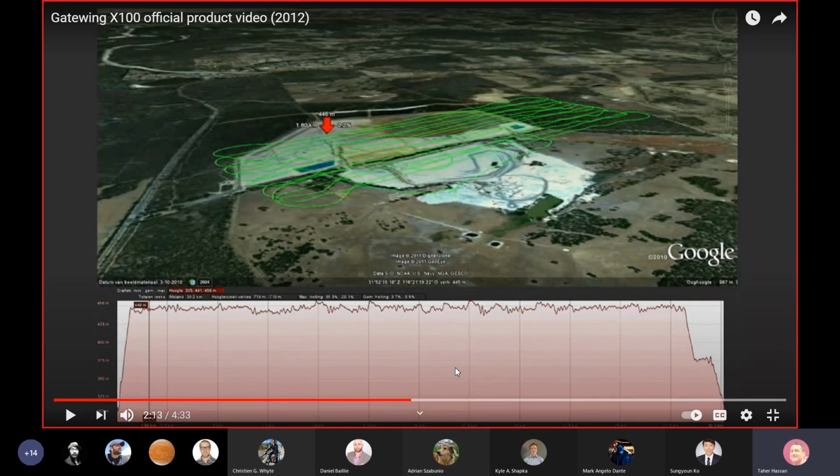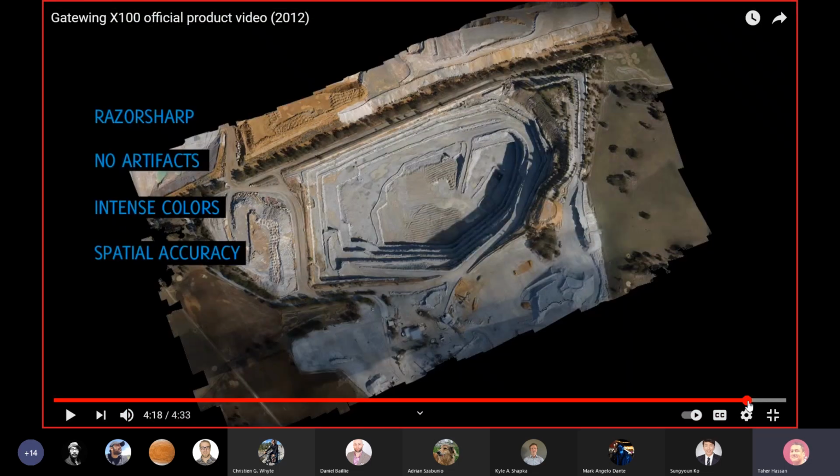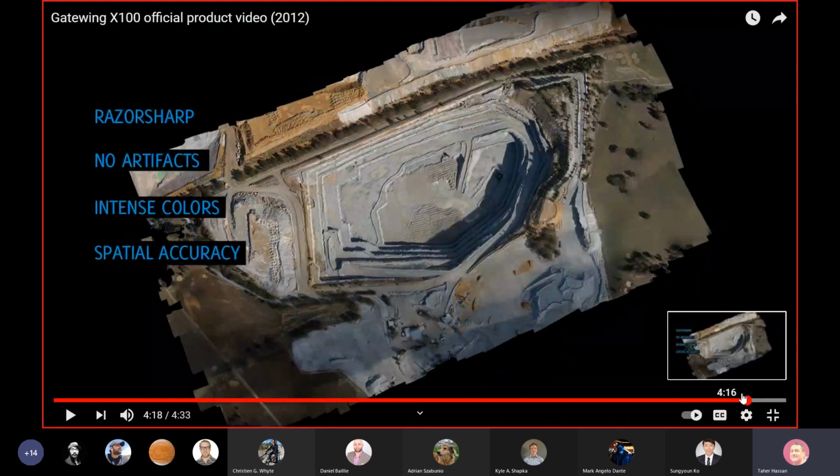So I would like to tell you that fixed wing drones are very compatible with linear projects. If you have a project, for example road design or power line survey, the best drone is fixed wing, because it goes almost in a straight line without wasting energy to turn on those radii. Okay, now let's move on to the last part, which is the product.